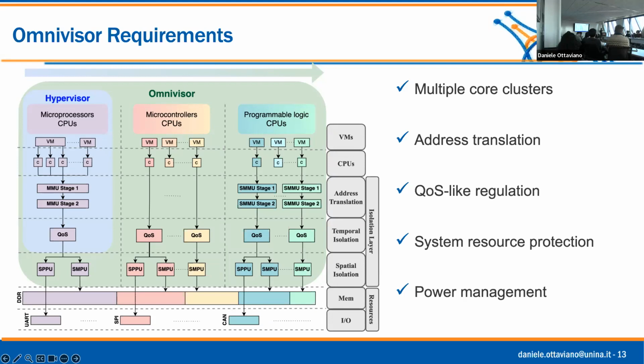They are not near the core like the MMU, but near the resource to protect. One of the resources is the memory, but other resources in the system protected by the MPU are, for example, the full power domain switch, where there are all the registers to change all this stuff. So you can simply program this memory protection unit to avoid access to a specific register, and so to avoid the FPGA taking control over the hardware.